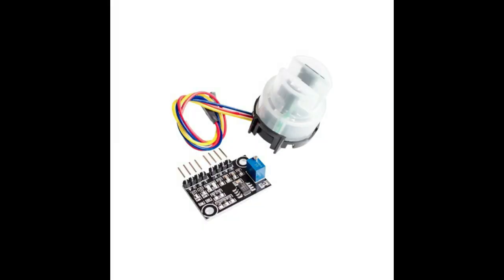The turbidity sensor detects water quality by measuring the levels of turbidity or the opaqueness. It uses light to detect suspended particles in water by measuring the light transmittance and scattering rate, which changes with the amount of total suspended solids in water. As the TSS increases, the turbidity level increases.